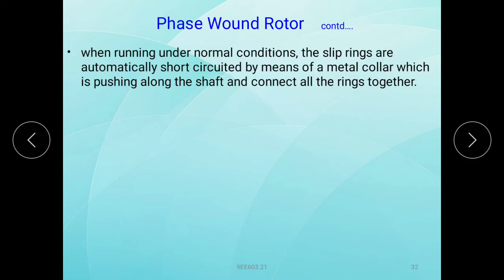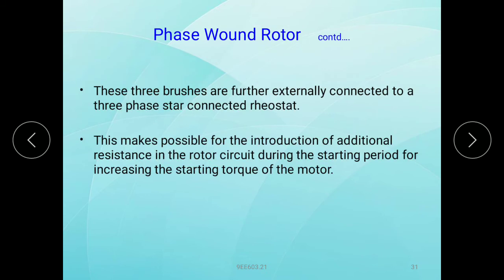These three brushes are further externally connected to a three-phase star-connected rheostat. This makes possible the introduction of additional resistance in the rotor circuit during the starting period for increasing the starting torque of the motor.